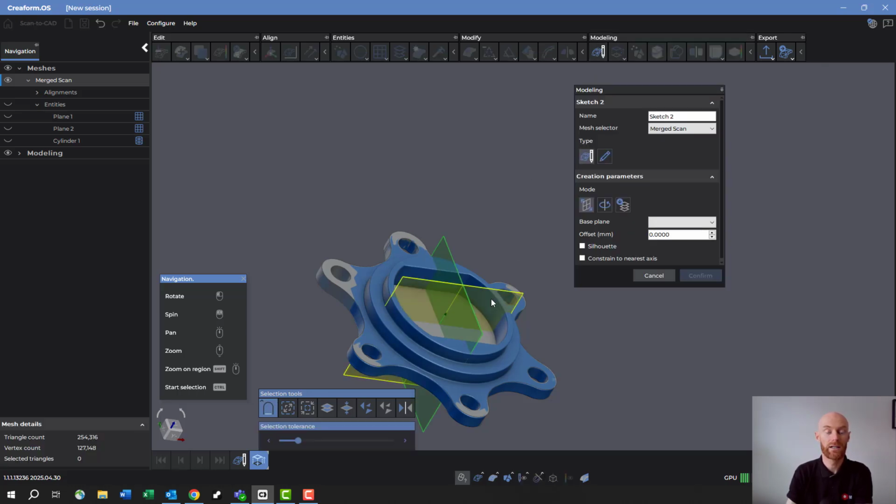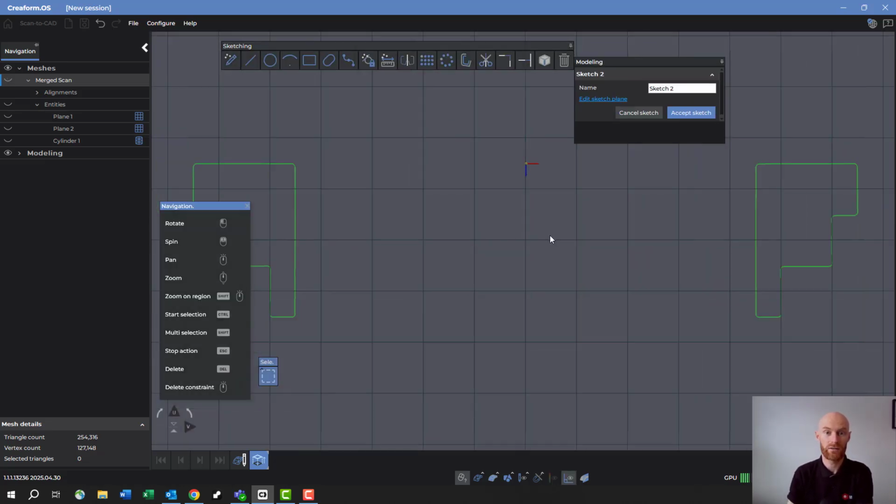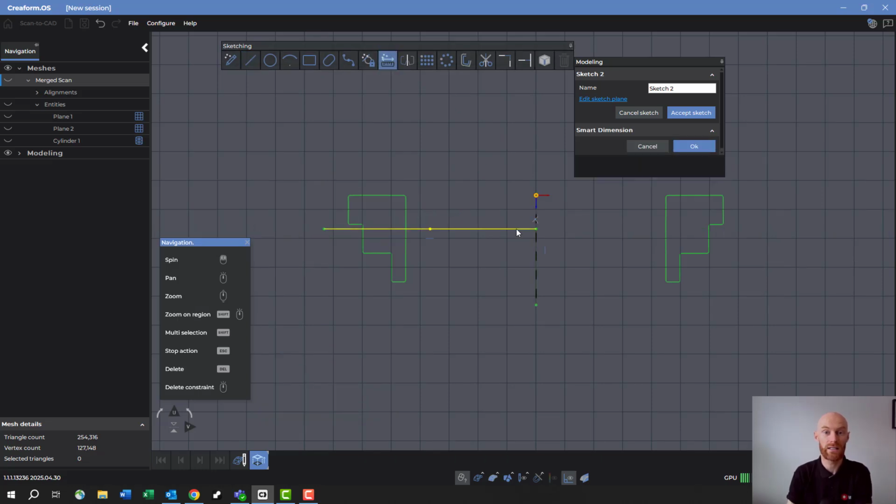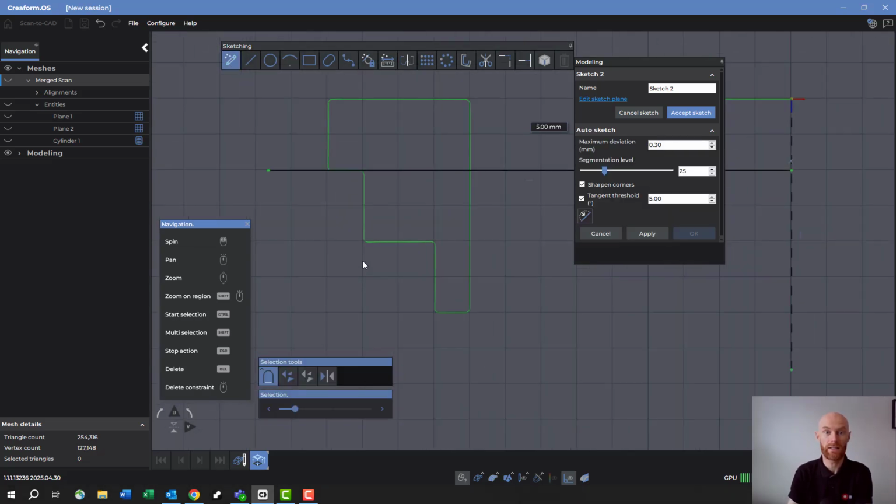The next thing we're going to do is create these 2 cylinders on the top of the part. Again, I'm going to use a cross section to give us some entities that we can start to work with. First thing to do is create a center line. It's going to be the center axis of our revolve, and I'm going to create a line on the bottom that's going to be the base of our sketch. Now I know this needs to be 5mm from the base of the part because that's where our previous model was, so I can add in a dimension here that's 5mm.